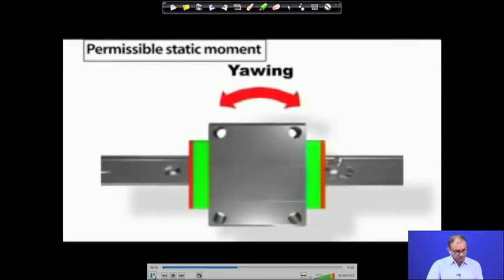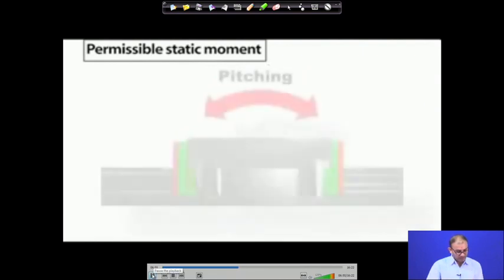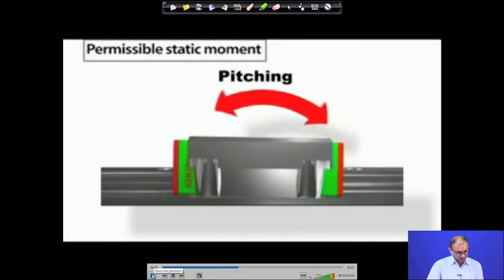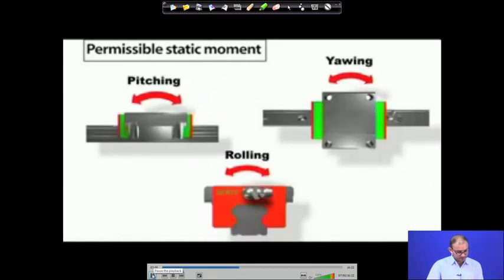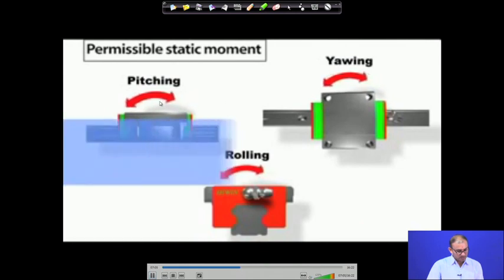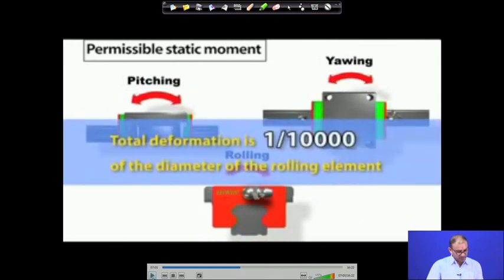Right. So, when you see from the top, then it is called yaw motion. This thing we have seen in the geometric error in machining. And this is called the pitch motion, that is looking from the left side or the right side. These are the motions that mostly happen when you are doing machining of side cutting, slot cutting, something like that.